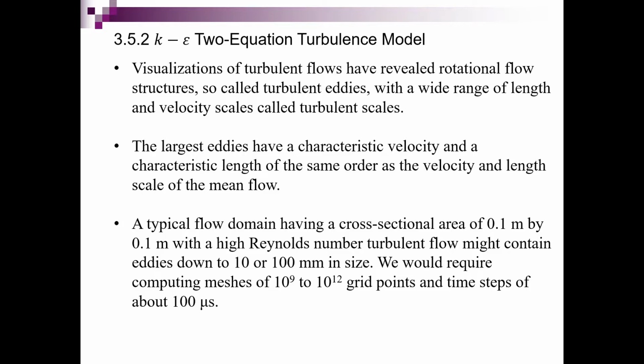And the same goes for the time steps, because velocity, as we know, is a function of time. Since the velocity has a very high range, we need to make sure that the time step is very small so that we can capture all the small vortices that are induced due to the turbulence.